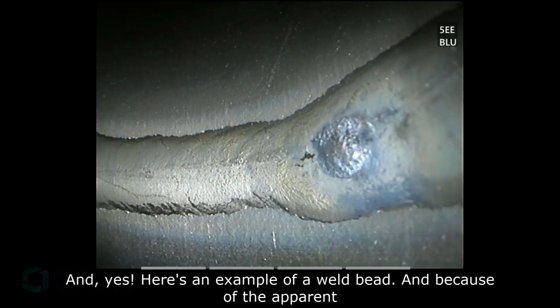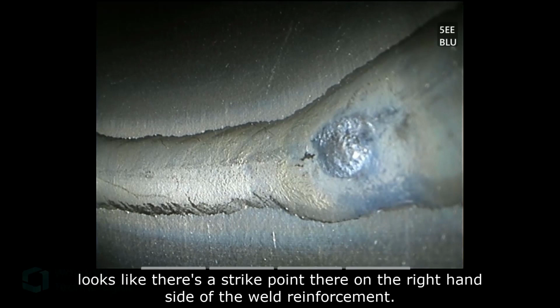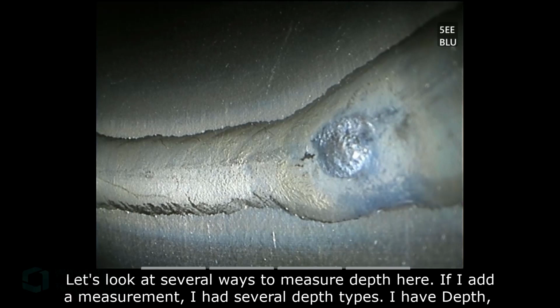And yes, here's an example of a weld bead, and because of the apparent curvature, I would say this is likely inside of a tube. It looks like there is a strike point there on the right-hand side of the weld reinforcement. So let's look at several ways to measure depth here.